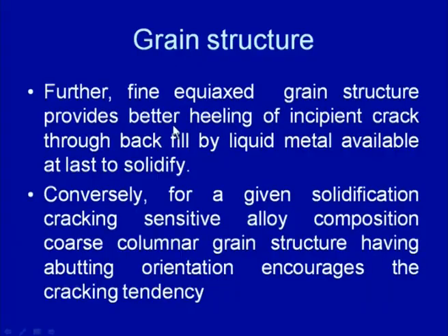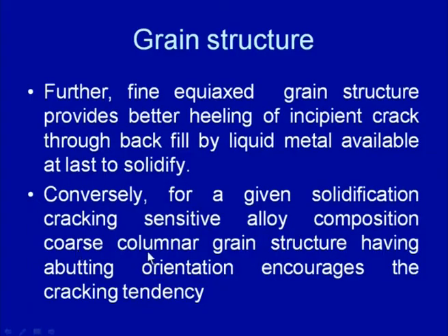So, this fine equiaxed grain structure will provide better healing of the incipient cracks through the backfill by the liquid metal available at the last stage to solidify, and conversely, for a given solidification cracking sensitive alloy, if we are having the columnar grain structure, then the cracking tendency will be more as compared to the case when we are having the fine